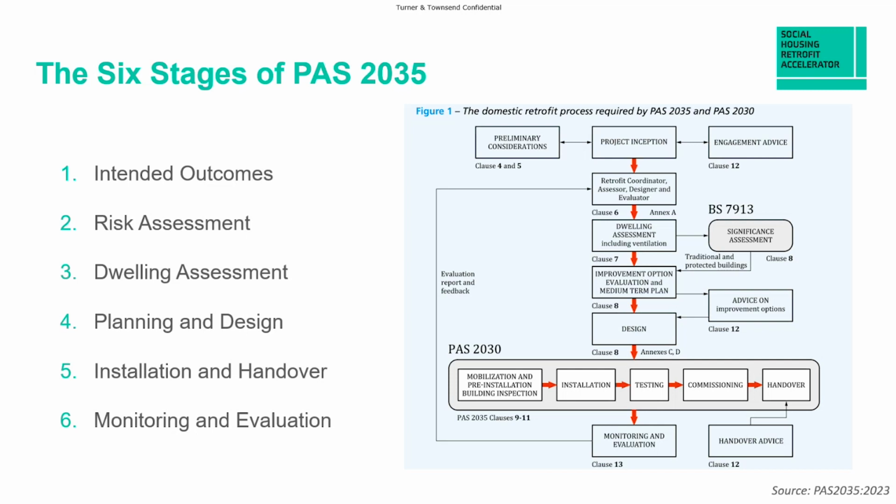They could be an EPC C as a result of the work that we've done, or it could be aiming for a kilowatt hours per year heating demand. So it was 90 under wave 2.1 and 2.2, trying to achieve 90 kilowatt hours per meter squared per year heating demand. So that could be one of your metrics.